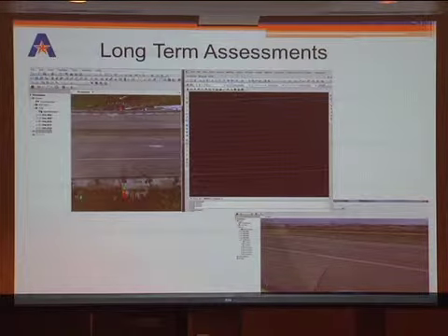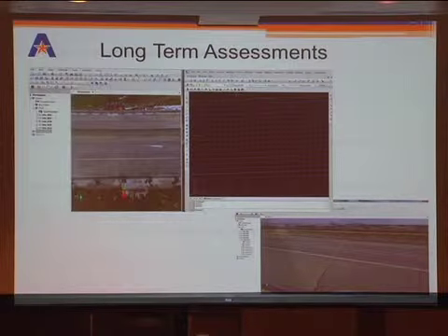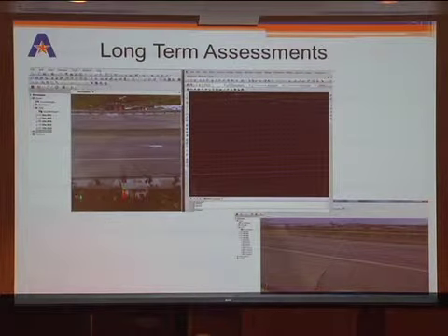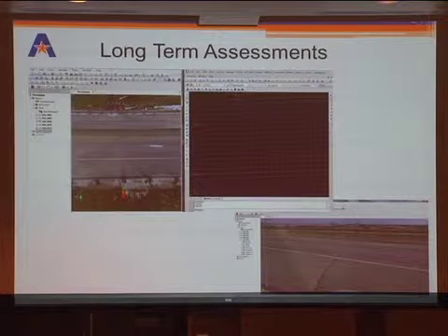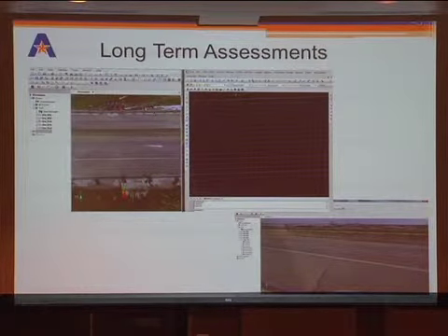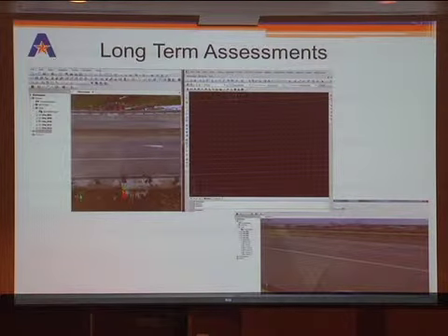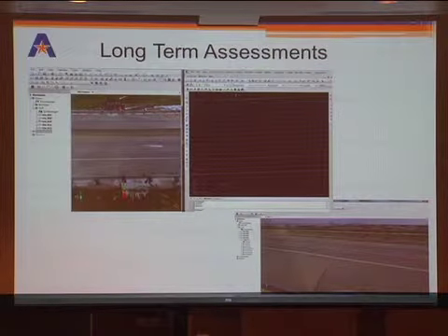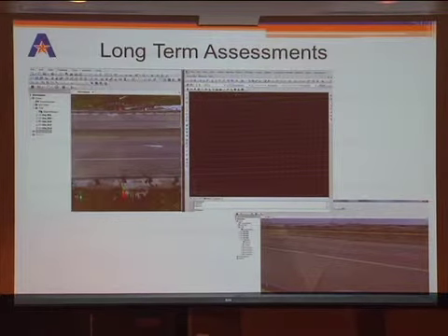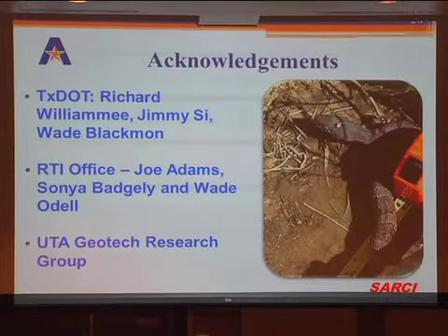So we are looking at this data to see if there is anything, and we're also looking at the profiler. We do see in recent data a small increase in our settlement. And again, in May, we had almost 20 inches of rainfall in that particular location. This small increase in settlement is only on 1 kilometer that we have noticed. We want to monitor that one. The total amount is very small. It's probably not going to make any difference to the roughness, and we won't even see any repair, but still we want to monitor it and see if we can learn from it.